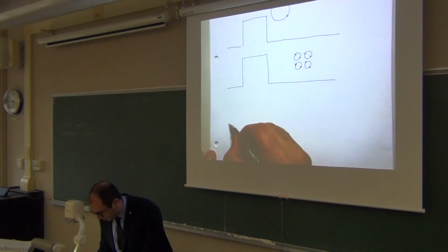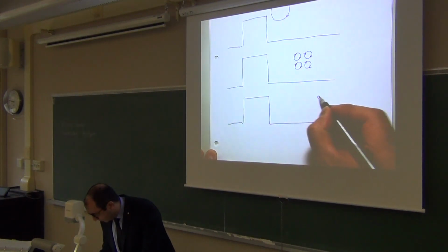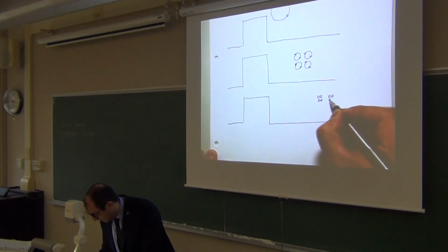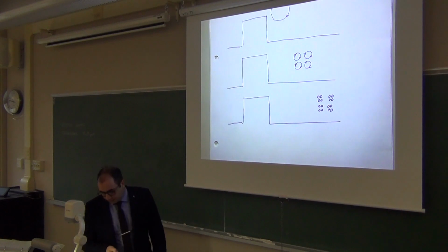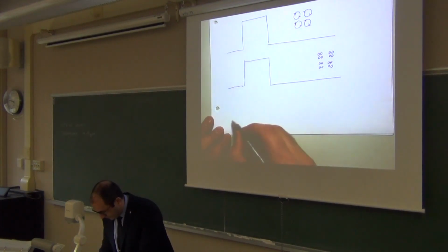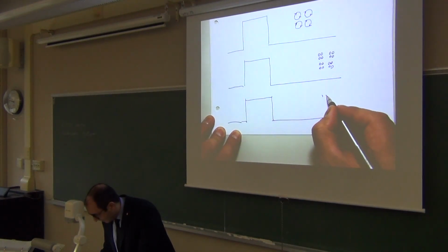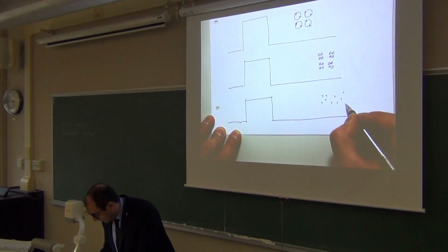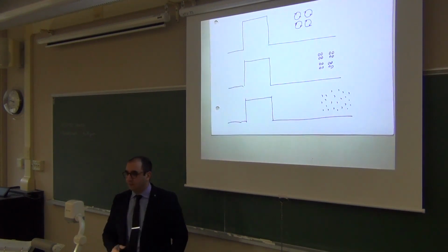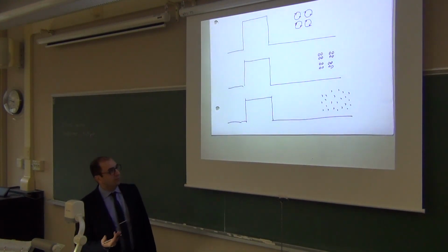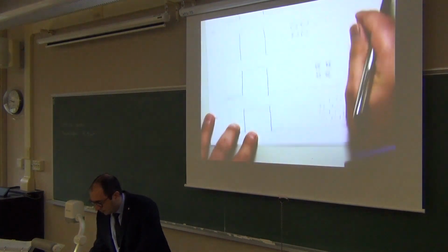And then further, smaller, each one then becomes 4, another 4. And then finally, it's so small that it cannot break down further. Then the energy of chaos in the momentum, let's say the kinetic energy of this eddy, the motion of this eddy, will dissipate into viscosity. So here you can say the eddy is breaking up.